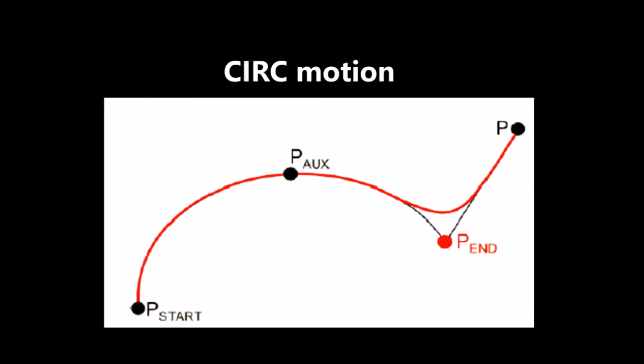The same concept goes for the linear motion function with approximate positioning. For circular motion, the program path will stop accurately at the auxiliary point from the start point, while the endpoint is approximated. By the way, the path in the approximate positioning range is not an arc.